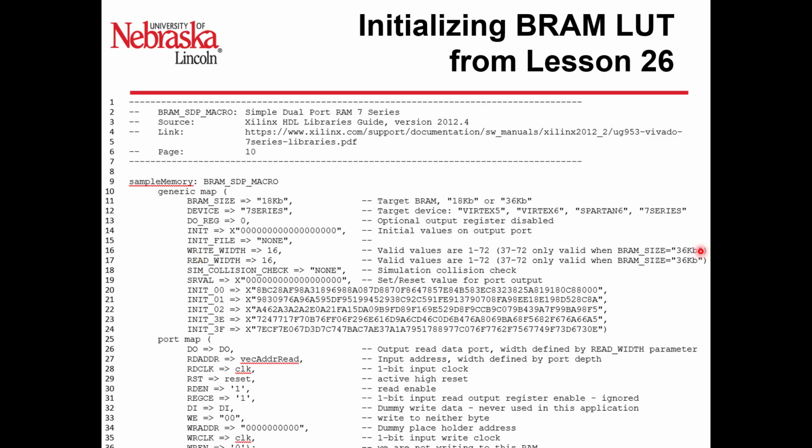Remember, for this VRAM initialization, it's very similar to what we did, except we're just adding these lines for init statements to initialize our 64 rows of memory, or 1024 words, 16 bits of memory. So right now we're changing the read and write width to 16 bits versus 18. Memory address 0 starts on the right, on the top. Memory address 1 counts to the left to 15. And then the next row is address 16, and it keeps going.